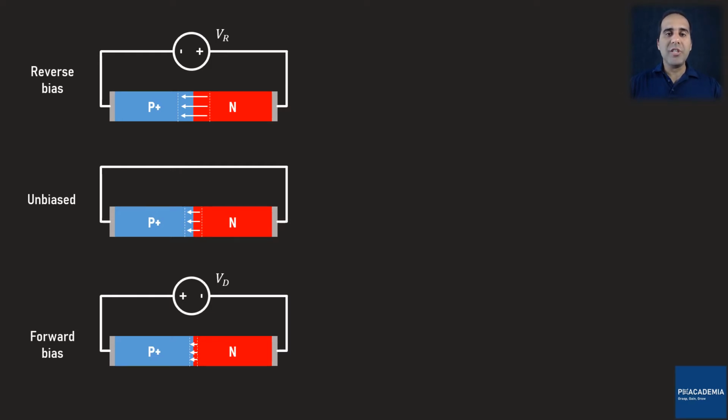The depletion region is free from any mobile charge carriers. At the edges of the depletion region, we have the accumulation of minority charge carriers. Therefore, you can imagine the edges of the depletion region as two facing conducting plates, which are separated by the depletion region. Soon we can realize that this is nothing but a capacitor that has a specific capacitance.